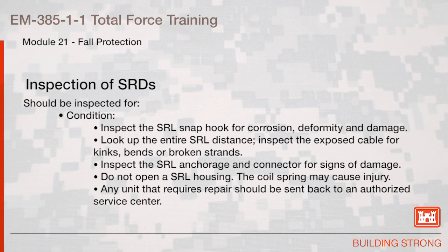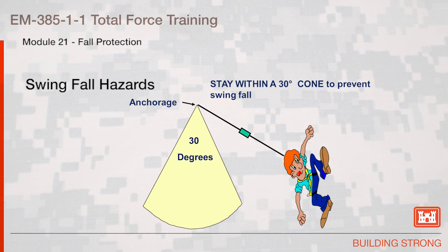Do not open the SRL housing. The coil spring may cause injury. Any unit that requires repair should be sent back to an authorized service center. Swing fall hazards. Stay within a 30-degree cone to prevent a swing fall.